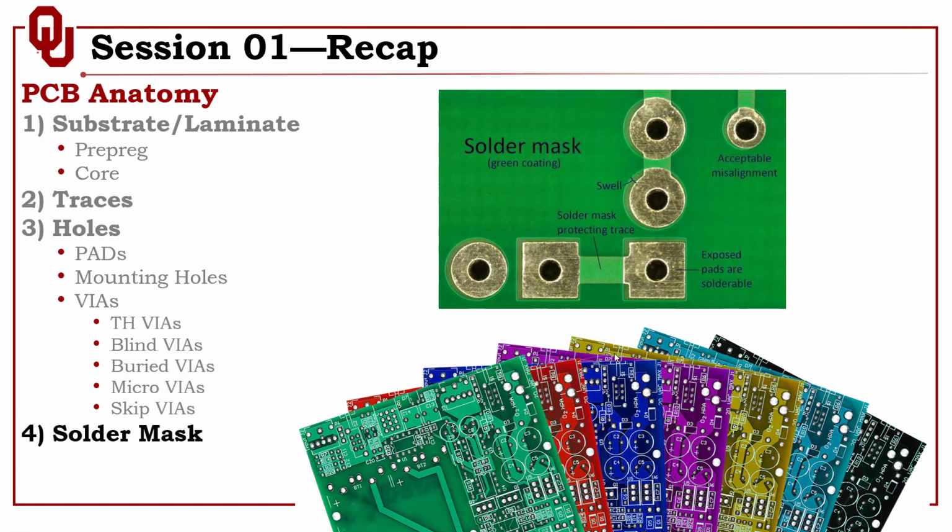They are available in different colors. I used to use red, for instance, for power electronics boards, and sometimes I used black solder mask when I have transparent fiberglass on the top of the product and I don't want the green to be exposed. So black will help me hide the PCB inside a little bit. You can pick the color you want.